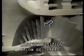As the engine speed reaches 66% speed, the vanes begin to move towards the maximum open position. This movement takes 8 to 10 seconds. The vanes are in the maximum open position when the engine reaches 100% speed, allowing air to flow through the engine at a maximum rate.